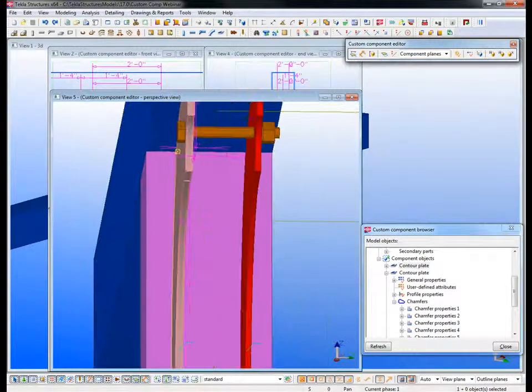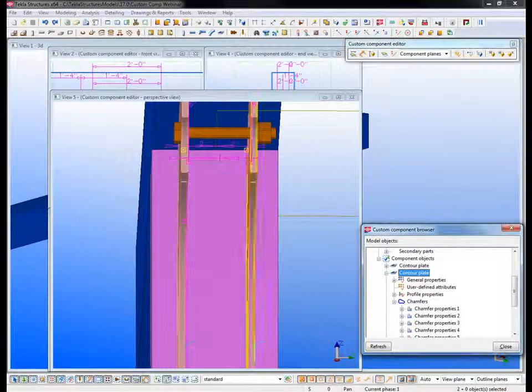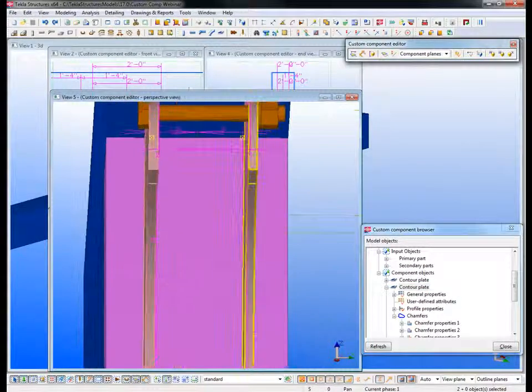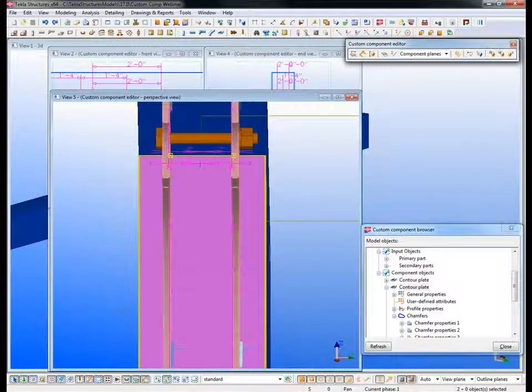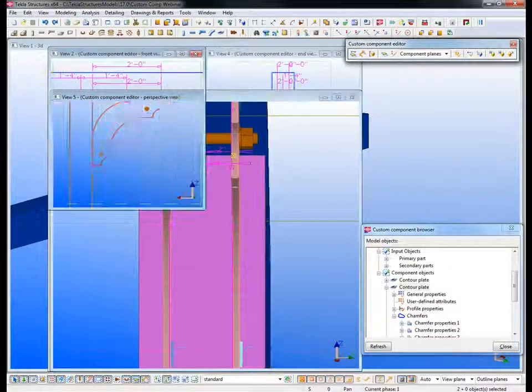Yeah. Going along with that, the way that I did model these in is, you see when I highlight, I modeled these in as contour plates, is that we're going to define a variable for the user to define the spacing here. And I have my bindings on the inside, so that the bind is from this handle on the inside to the center of the column. So when we create our variable, we can just create an equal space, and it will just fluctuate that way.